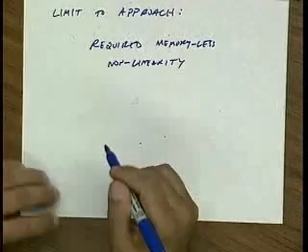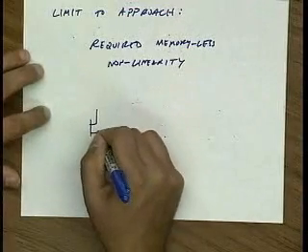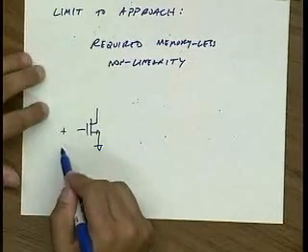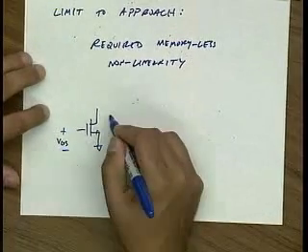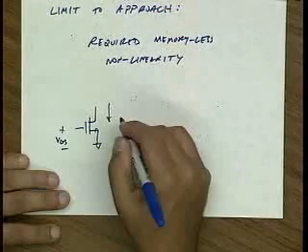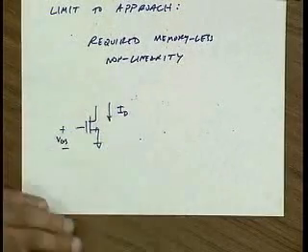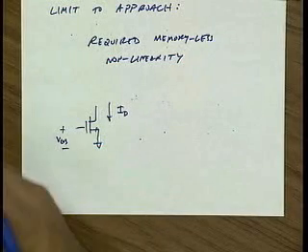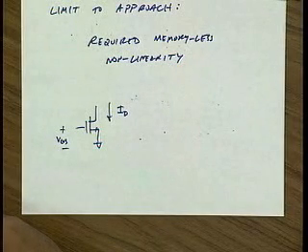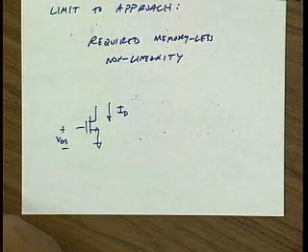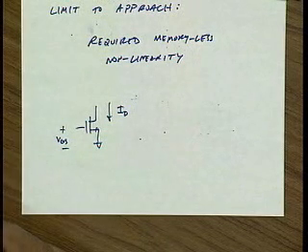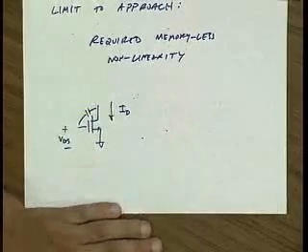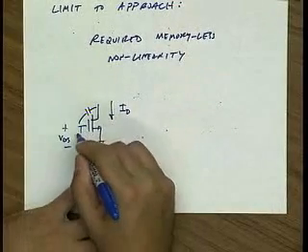Let's look at a transistor, right? Let me look at a FET and consider applying a large signal VGS here and what kind of current it generates. Now, what kind of elements inside this FET would generate distortion that has memory in it? Yeah, the capacitors, right? Everything else is memoryless. So I have this small overlap capacitance, right? I have a CGS here.